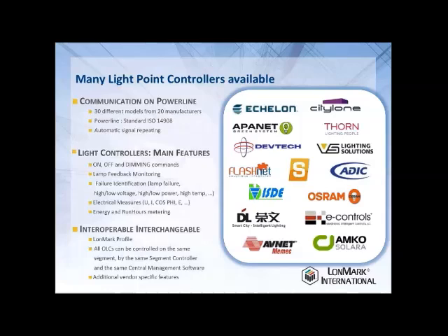And again, all these different hardware are talking with the same protocol to provide the features which are listed on your screen, mainly on, off, and dimming commands. All these devices are providing stepless dimming commands, while some proprietary systems are still working with discrete dimming commands. So let's say enable you to dim the light at only 50 and 70%, for example, while here we are talking stepless dimming, any percentage between 0 to 100.